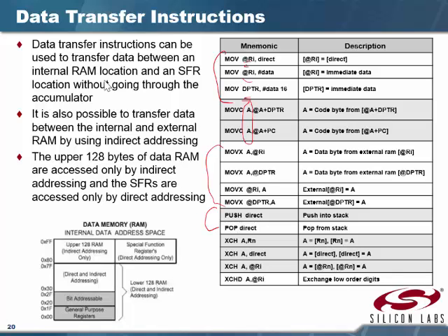When we start writing some C code toward the end of the class, you're going to find that you could do it either way. But what's pushed onto the stack is going to be either the address or the data itself. If you pass the address, then every place you talk about it in the function, you're going to be using relative addressing because the address is contained there. If it's not, you're going to be using direct or immediate data. So there's some variations, and that's one of the reasons why you have so many addressing types, because when you start writing subroutines in high-level languages, the compiler will use a lot of these.